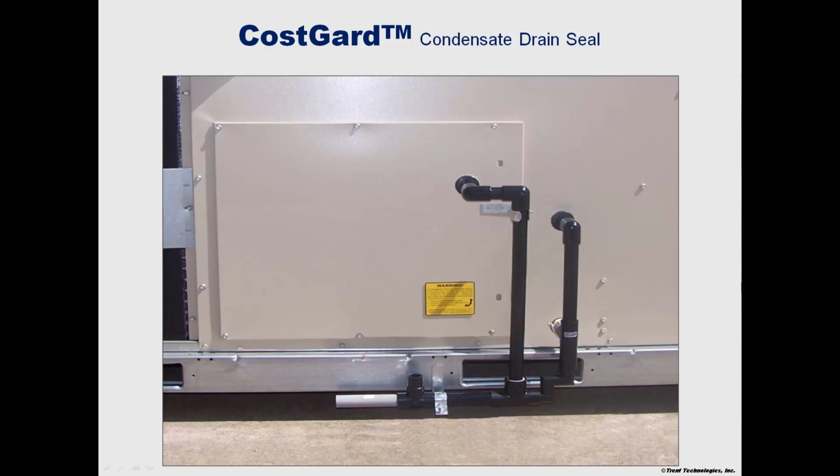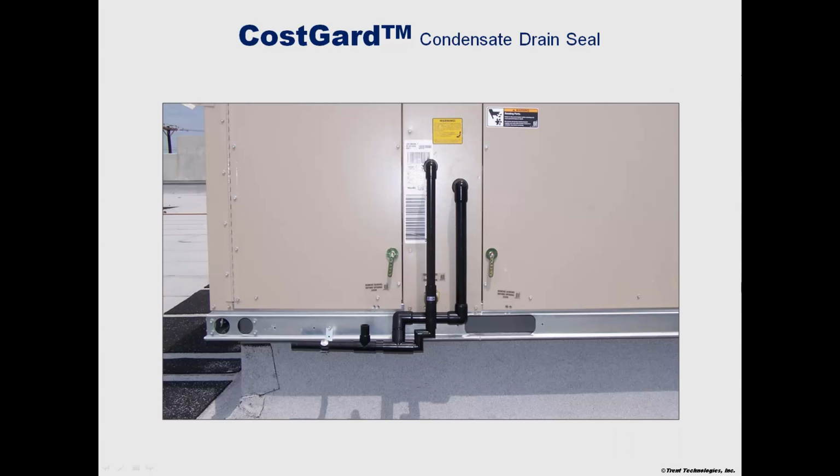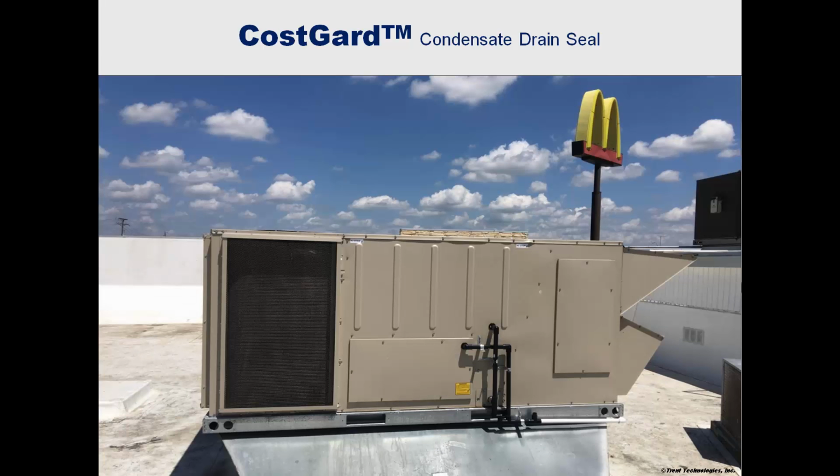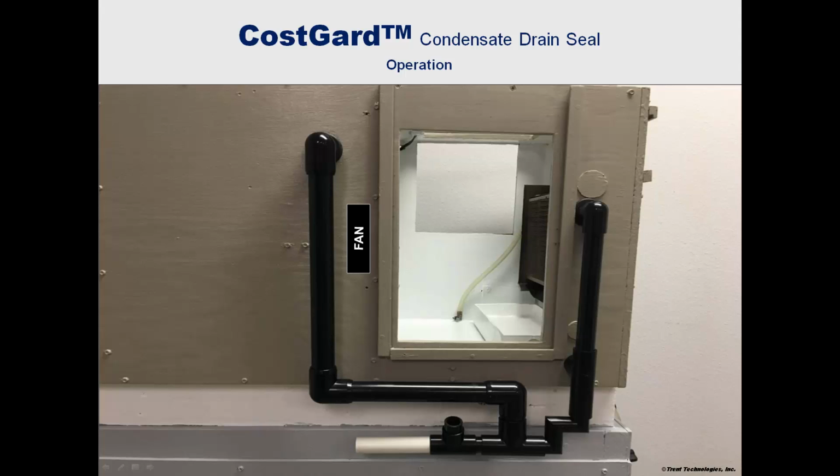This seal protects the building owner or user against undue cost in terms of maintenance effort, property damage, early equipment replacement, and health care. For this reason, the word CostGard is used to identify this seal. How the CostGard Condensate Drain Seal functions can easily be explained by the use of a simulated air handler. A small quantity of air is taken from the positive pressure side of the fan. A portion of this air is discharged through the condensate drain pipe to ensure that outside air and pollutants are not drawn into the system.